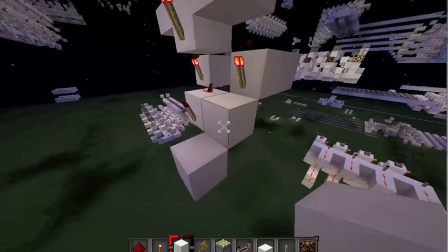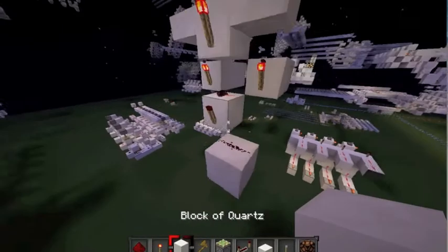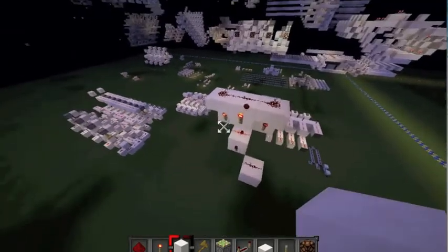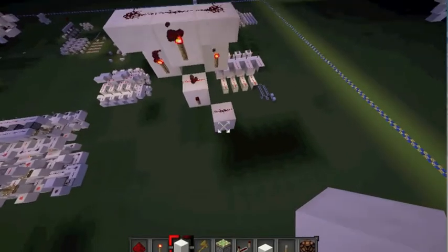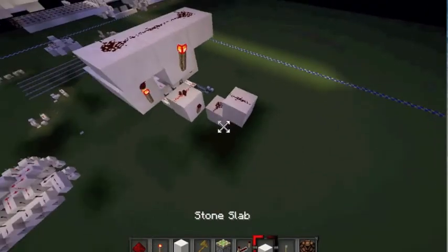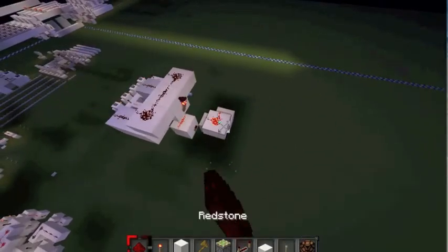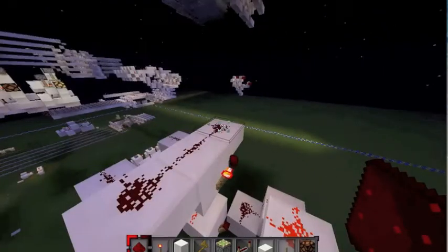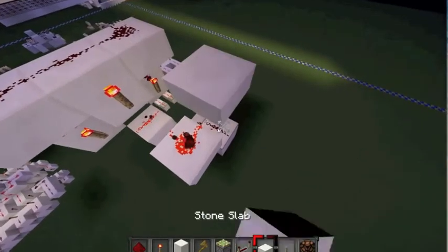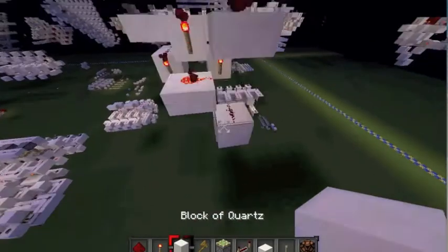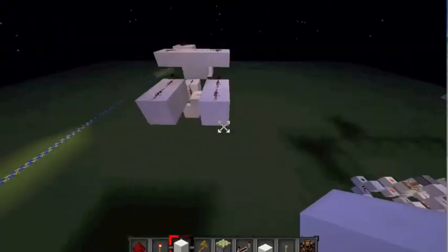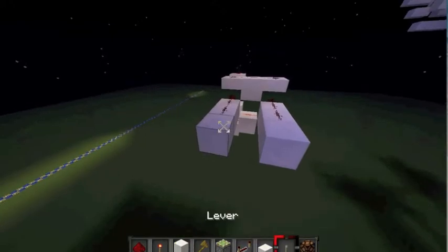So now I'm going to take power from this AND gate down here. By the way, the reason I've done this is I need a NOR gate and an AND gate in order to make an actual XNOR gate, which I'm going to be using as the half adder in this. Also slab, so that a whole bunch of stuff doesn't conflict. But anyways, now I have managed to OR these together, so this data right here should, if I've done everything correctly, act as an XNOR.